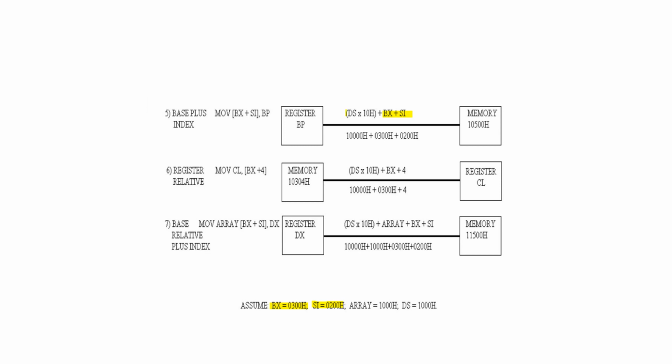That offset address I am going to add with the segment address. Already told you the segment address is 1000. That will be multiplied with 10h, so I will be getting 10,000. That is indirectly left shifting 1000 by 4 bits, which gives 10,000. These two will be added: the offset address 0500 with 10,000, I will be getting 10500, nothing but a 20-bit address, with the help of base index addressing.